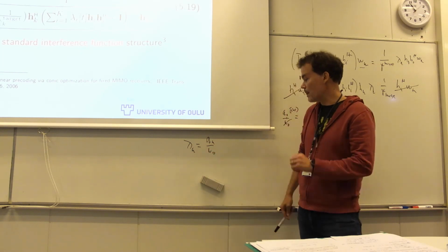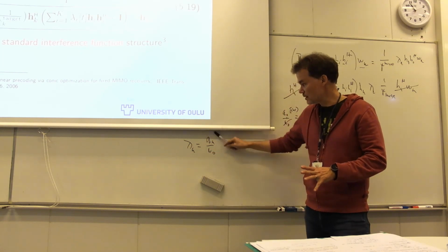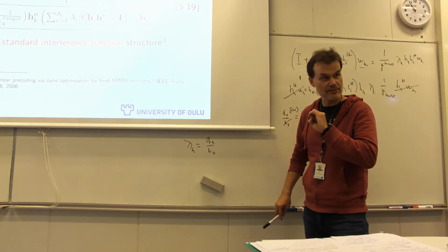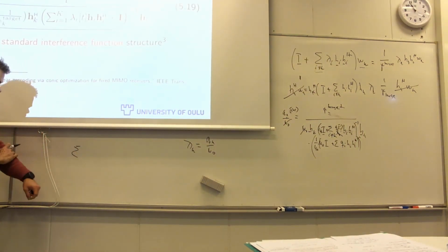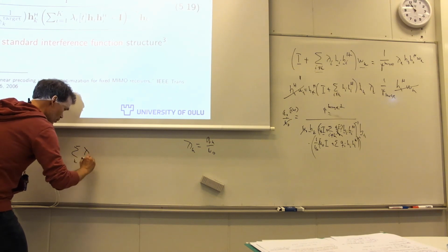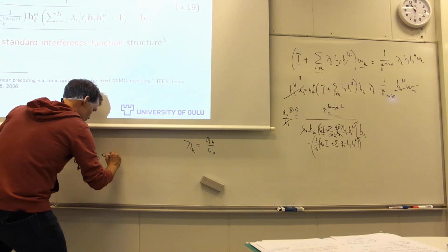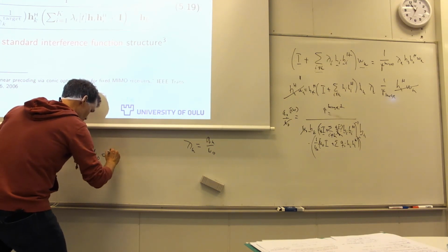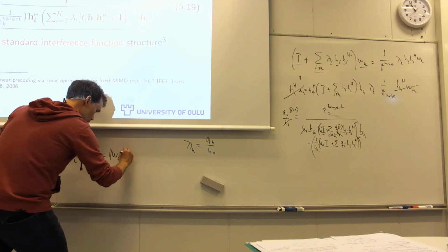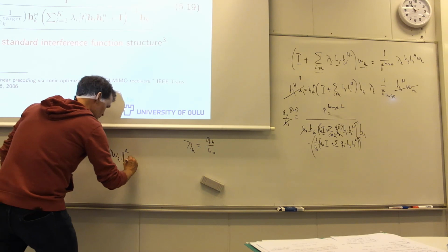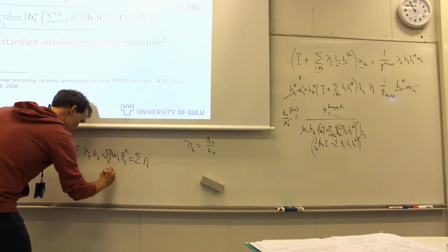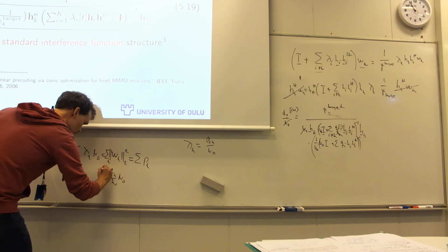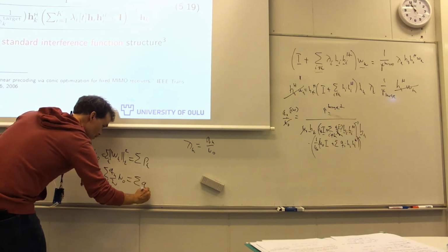So these dual values can be interpreted as noise normalized dual uplink powers. So we have also, of course, when you look at the primal dual, the duality gap has to be 0, meaning that sum of lambda k n0 equals sum over pk, and this equals, of course, qk over n0 times n0, equals sum over qk, right?